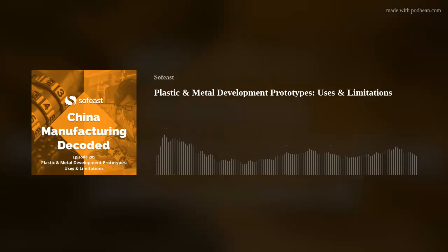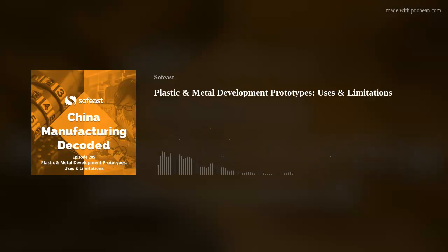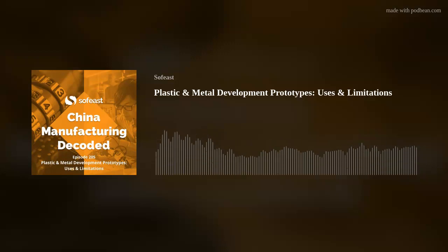We've touched on material properties, which is the next point on the list. And I've said here, CNC machining offers a close material representation of prototypes, but they lack exact mechanical properties. Now, when we're talking about exact mechanical properties, if you're looking at a high pressure die casting, and if you look at that as a cross section under a microscope versus a billet, it's going to be very, very different. Okay, they offer different mechanical properties. So again, this is a limitation.